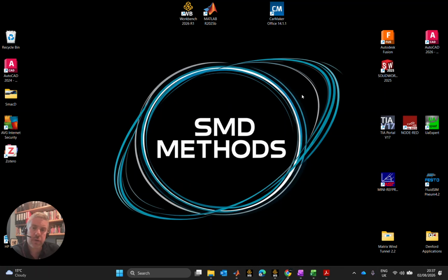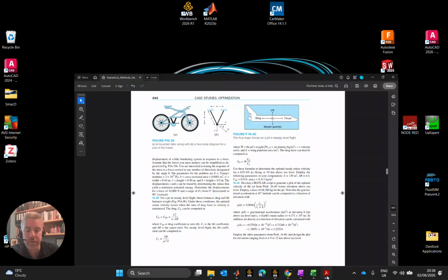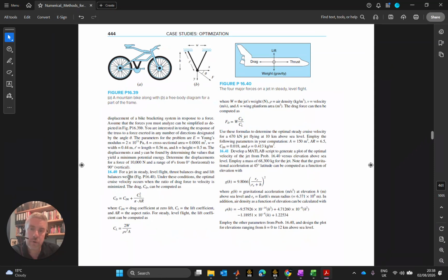You're very welcome into this video in which we're going to look at an optimization problem as set out by Steve Chapra in his 8th edition of Numerical Methods for Engineers. Problem 16.40 sets out a challenge to determine an optimal cruise velocity for a jet at a given elevation. Although the elevation itself is not provided in the problem, parameters which would represent the height are, such as the density of the air in which the jet is traveling, and indeed the acceleration due to gravity at that elevation, which in itself is embedded within the weight of the jet given in the problem.